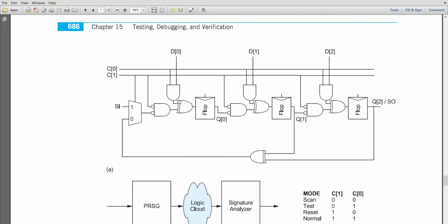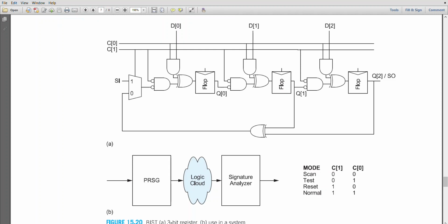So whatever data you are providing for scanning will be shifted from here to here to here to here, and then this output is again taken to the XOR gate, and here the n-1 output is taken, XORing will happen, and then again it is applied to the 2:1 multiplexer, and accordingly 1 or 0 is again supplied here. SI means the serial in data, and this is the serial out data. Okay, so this is how built-in self-test techniques are designed.